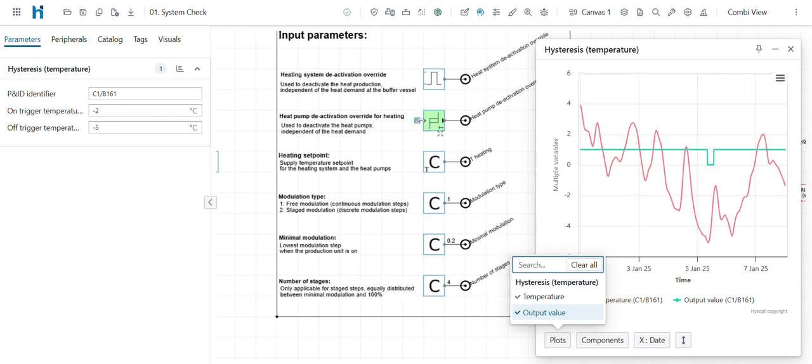Okay, so here a few different things we could do to solve this. Either we could put perhaps a larger buffer tank in order to try and bridge that time at which the installation is smaller than -5. We could take away this safety. Of course, this is just trying to protect the COP of our heat pump. We could also install a hybrid system where we would have a boiler as a backup if the temperature goes below a certain temperature. All those are valid solutions.